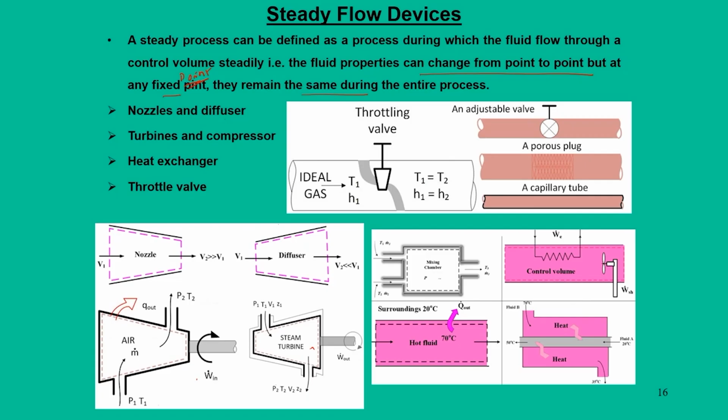A heat exchanger does not have a role in producing power; it mainly deals with the interaction of heat. We can have two ways. When you say it is a control volume, two fluids can mix each other, so you can have a mixing chamber, and the combined fluid can leave. That is one way. The other way is that we pass the two fluids through two different entities and they do not mix, rather they only exchange heat. That way we call this a heat exchanger.